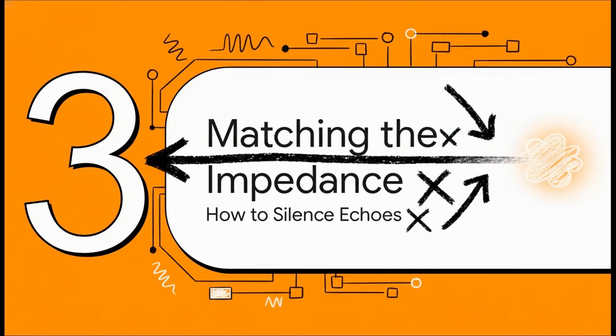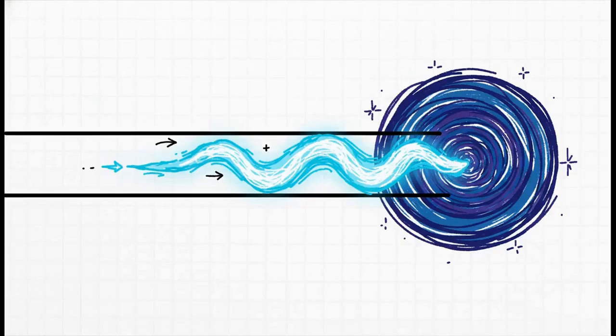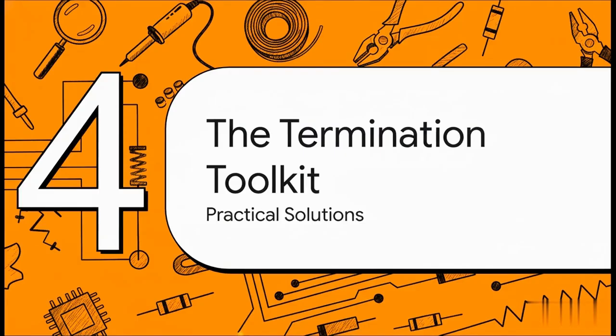So the million-dollar question is, how do we stop these echoes? How do we silence them? The goal is to make sure that when the signal gets to the end of its journey, it doesn't hit a wall. It needs to end smoothly. And the way we do that is, honestly, kind of brilliant. We basically trick the signal into thinking the line just goes on forever. We do this by making sure the impedance of the component at the end, the load, perfectly matches the characteristic impedance of the line. When they're the same, all the signal's energy gets absorbed. No mismatch, no reflection, no echo. Problem solved.